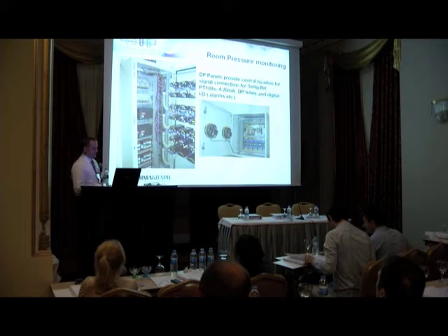And lastly, we have a CC2004, which again is 4 digital inputs, but it also has 4 digital outputs, which we can use to drive alarm tower stacks, volt-free contacts to other systems, and so forth, whatever you want to do with them, really. So we just got another sort of system overview.